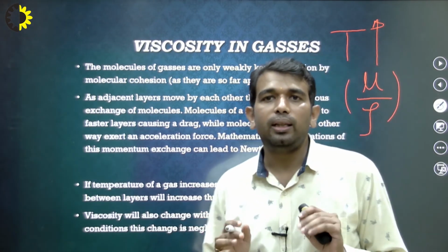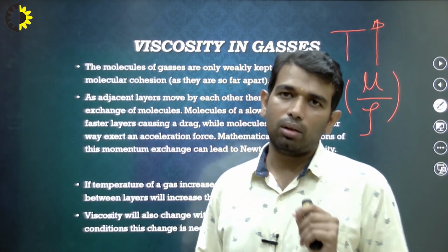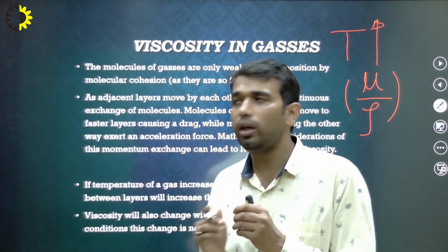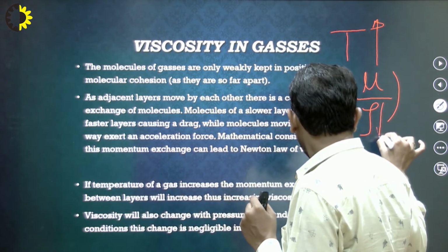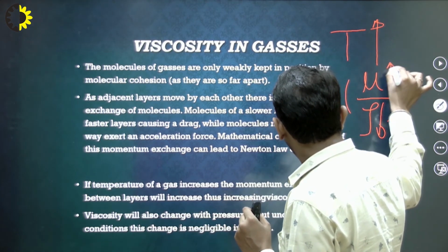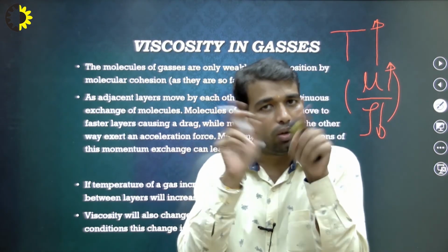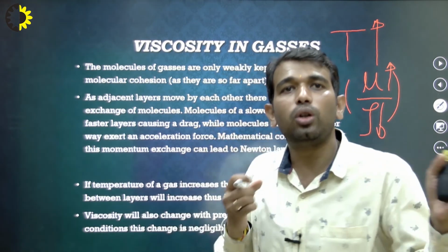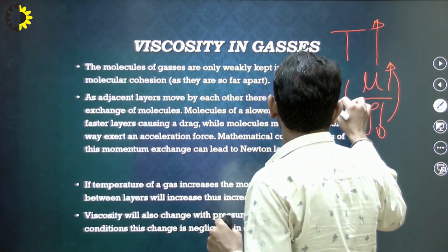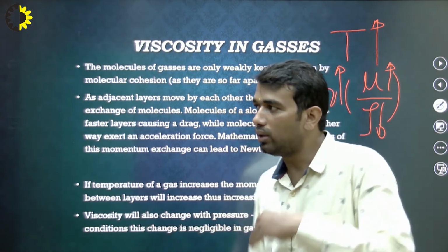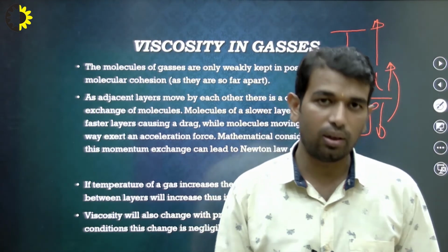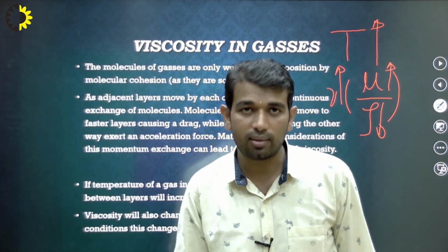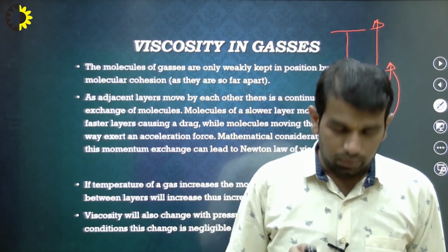When you increase the temperature, molecular collision is going to increase, that is true. But when you increase the temperature, the density of gases is going to reduce. So this parameter is going to reduce and the viscosity is going to increase. Because the temperature increases, molecular collision increases, so dynamic viscosity is going to increase, and further the density is going to reduce. It means the kinematic viscosity is going to increase further in magnitude. The change in the kinematic viscosity is quite a bit more compared to the dynamic viscosity; that is the basic understanding we should have about the viscosity of the fluid.